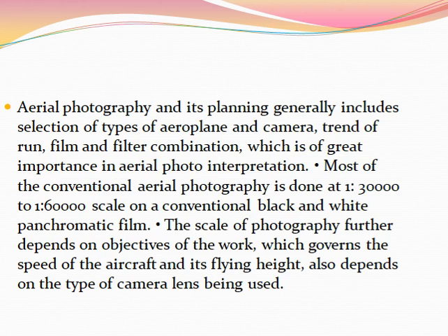Low flying speed and height are among the most important aspects in obtaining sufficiently large scale photographs with sharp images of objects. There should be complete stereoscopic coverage of terrain, that is, all features of terrain should occur on at least 2 photographs for stereoscopic viewing.